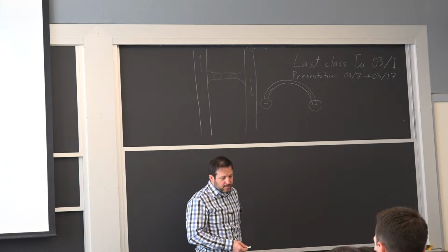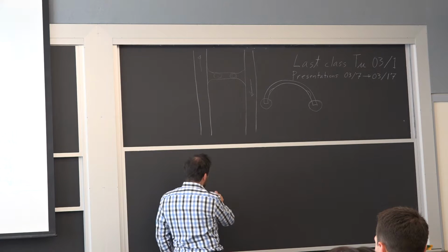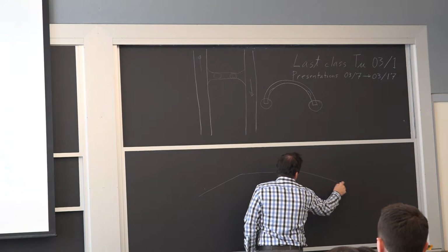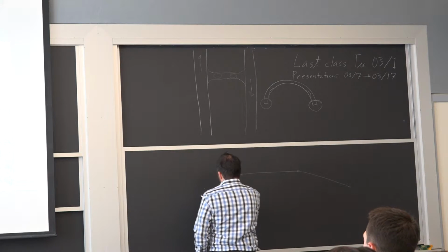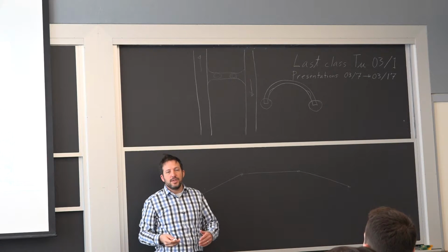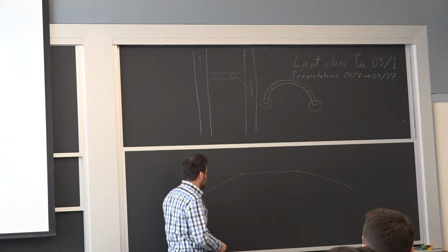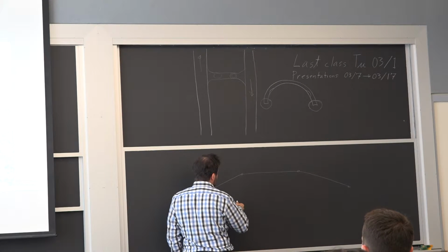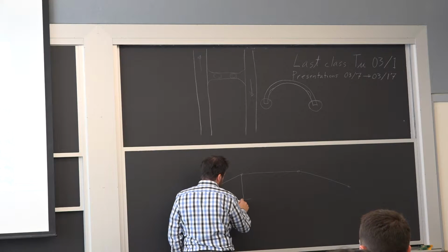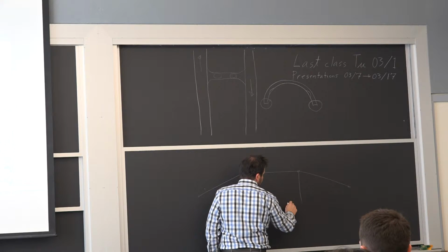So what happens to these trusses? They are very, very long. So you go from one side of the bridge to the other, and I won't draw the truss structure, but let's say we have multiple spans, and then we try to cross, and this is all steel. So from seasonal variation, it will try to expand and contract as opposed to the shores. And the way to accommodate this is expansion joints. So over here, if you go to the foundation, you have a roller system that's going to allow for the bridge to expand. And this one, let's say it's going to be fixed.